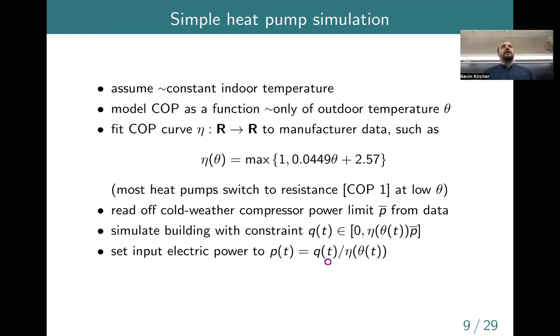Okay, question. Curious, for a variable speed unit, as compressor speed increases, what does it look like in here? Yeah, so the question is, if you have a variable speed heat pump, which rather than having a motor that's either on or off, would have one that can sweep through a fairly continuous range, and you add dependence on the compressor speed to the COP, what does it look like? So there, maybe I should have included a graph of that. Maybe I could add one to this. But there, what people talk about is what's called a part load ratio and a part load performance curve.